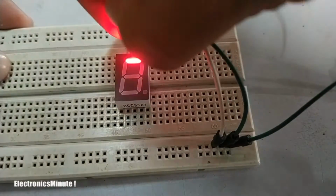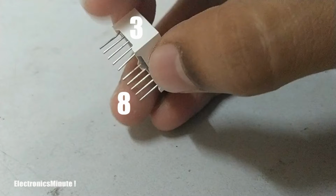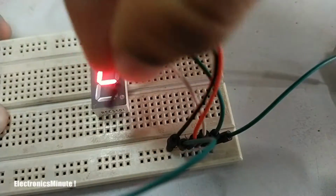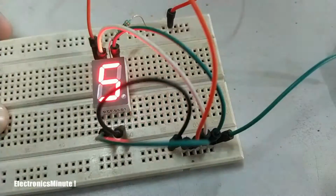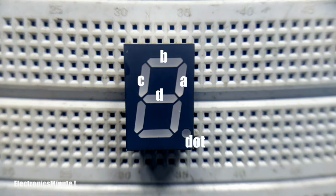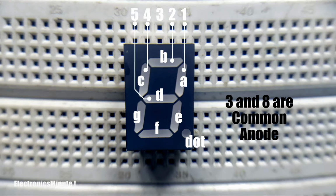Mine is common anode, and pins 3 and 8, the middle pins both on the top and the bottom, are common anode and the rest are the cathodes for different segment LEDs. I have mapped them in the following manner. Upright and the following are A, B, C and D, and bottom right to left are dot, E, F, G. Pin 1 is connected to LED segment A, pin 2 to segment B, pin 4 to segment C, pin 5 to segment D, pin 6 to the dot, pin 7 to segment E, pin 9 to segment F and pin 10 to segment G.